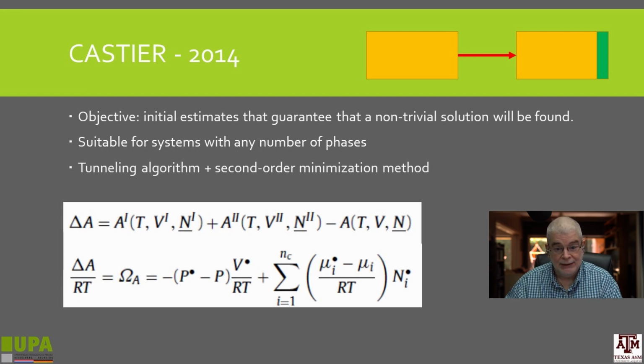So the point of doing it the way I suggested is that the phase stability test in a flash calculation plays two roles. One is to decide whether it's stable or unstable. This is the most obvious one. But then there's a bonus when you do this, which is to generate good initial estimates for the calculation with two phases.